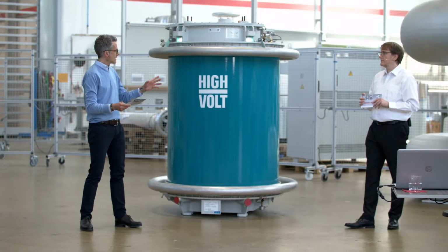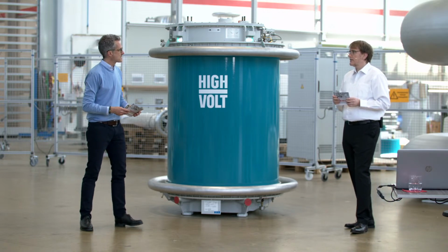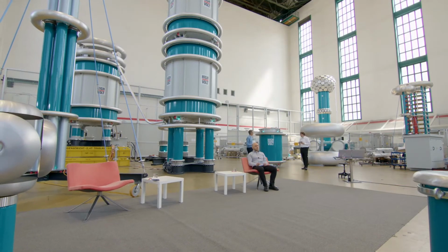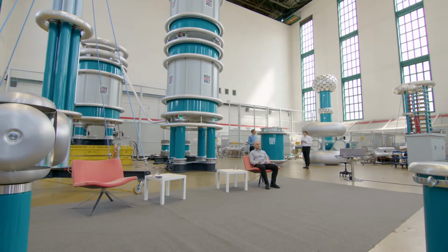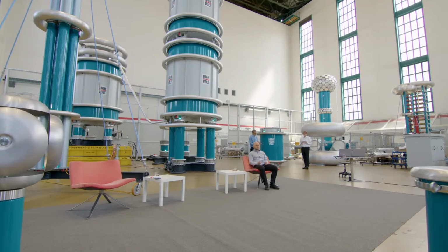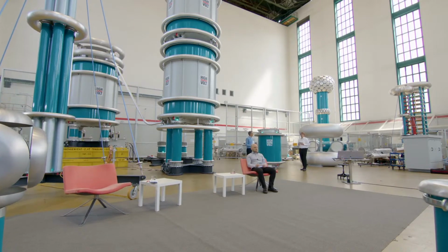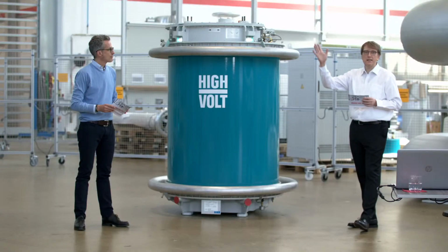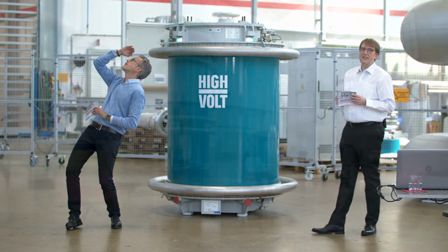But first of all, we have test equipment, of course, for cables also in the background. Beautifully designed. What do we see? What we see here between the two of us is a DC module worth 200 kV DC, both polarities. Out of that we can build up larger configurations. The largest one was 2.2 megavolt DC we have done in the past. And the large unit, maybe we can get the total view as well. Oh yeah, it's pretty high.